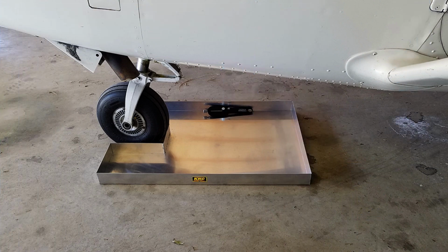To weigh an aircraft that does not include the engine lubricating oil as part of the empty weight, place it in level flight attitude, then open the drain valves and allow the oil to drain out. Any remaining is undrainable oil and is part of the empty weight. Aircraft certificated under Title 14 of the Code of Federal Regulations, 14 CFR, Parts 23 and 25 include full oil as part of the empty weight. If it is impractical to drain the oil, the reservoir can be filled to the specified level and the weight of the oil computed at 7.5 pounds per gallon.